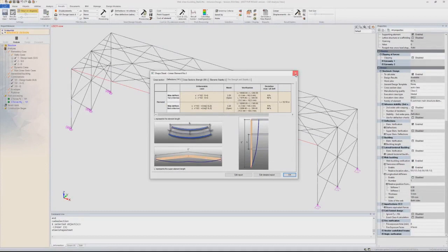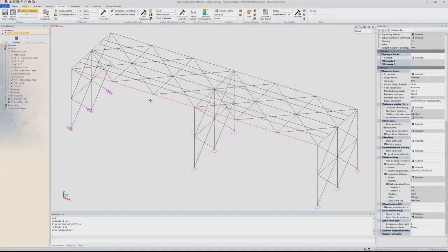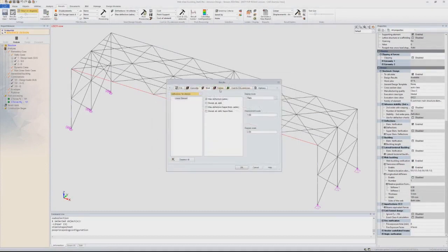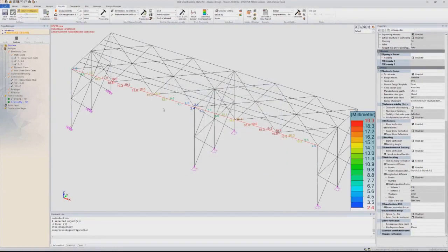And it's definitely a deflection in span, which is legit for a beam. And if you want that graphically, when choosing the results, make sure not to ask for a ratio, but switch to values, and that way you will get the deflection in unit length. So here we're getting 19.3 millimeters in span, just as expected.